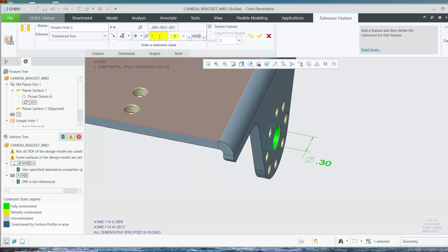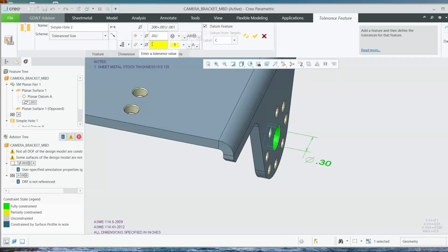Now we do the tolerance for the diameter. So again, I'll just say it's maybe 2/1000ths. Because it's a hole, I'm going to say maximum material conditions for this guy. Now I might want to put in another tolerance as well. So I can come over here and say, now it picks parallel. So by looking at the other things, and this is really considered an orientation tolerance, but I'm going to say it's parallel to A. So it's automatically found that.